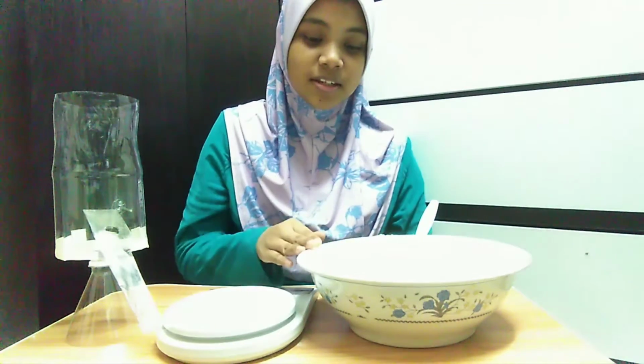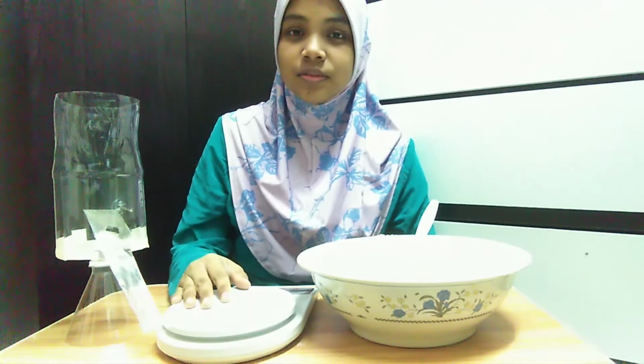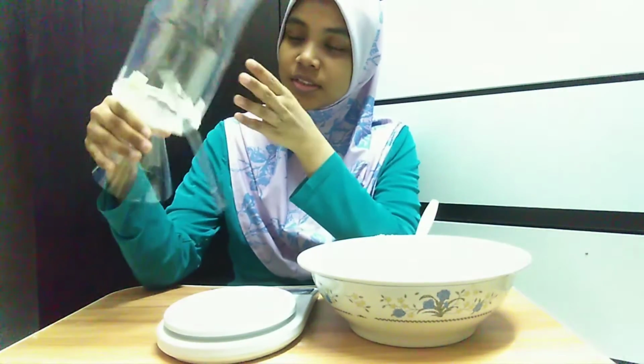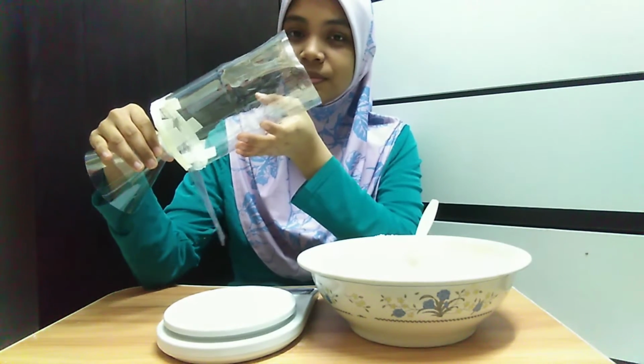For the field density test, we will use the sand replacement method, which needs sand, a sand pouring cylinder, and a balance. Firstly, we need to find the density of the calibration cylinder by using its mass and volume.